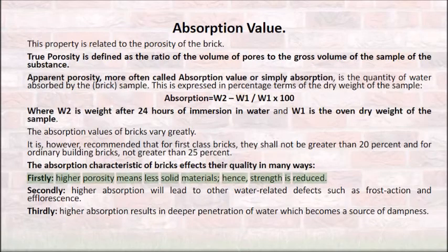Firstly, higher porosity means less solid materials, hence, strength is reduced. Secondly, higher absorption will lead to other water-related defects such as frost action and efflorescence. Thirdly, higher absorption results in deeper penetration of water, which becomes a source of dampness.